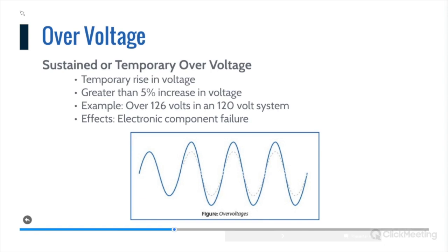And the cause of this is generally, there's several things. It can be a misoperation of utility equipment, the voltage regulators that are providing you the constant voltage. But it can also be a huge drop off of load for the utility. Whenever that large load drops off, the voltage automatically spikes and it's too soon, too fast for the regulation to catch up to it. It takes a few seconds for that regulation to actually change taps in a tap changer and get the voltage right. So it's not something that the utilities can exactly instantaneously control.